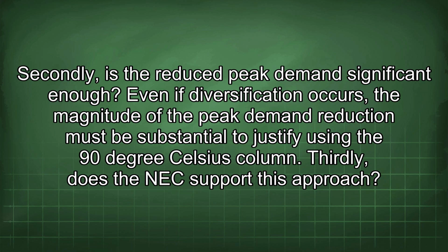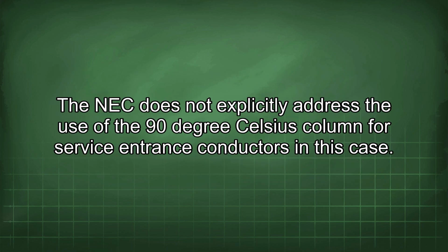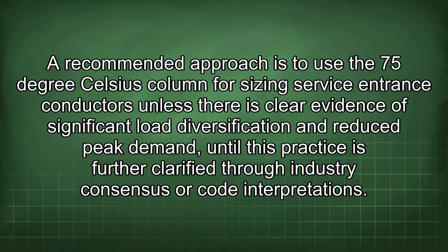Thirdly, does the NEC support this approach? The NEC does not explicitly address the use of the 90°C column for service entrance conductors in this case. A recommended approach is to use the 75°C column for sizing service entrance conductors unless there is clear evidence of significant load diversification and reduced peak demand, until this practice is further clarified through industry consensus or court interpretations.